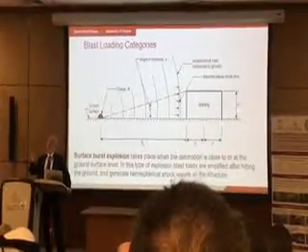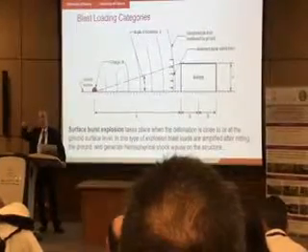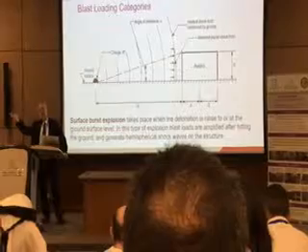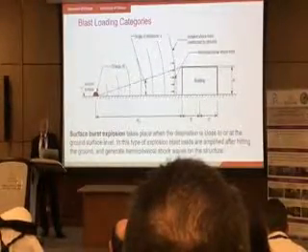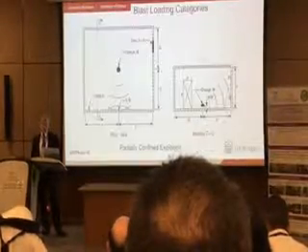So this is now called incident pressure in the air. It travels in a semicircular manner. It hits the building, it reflects, it increases 2 to 12 times the incident pressure. So these are dependent on where the explosion takes place.